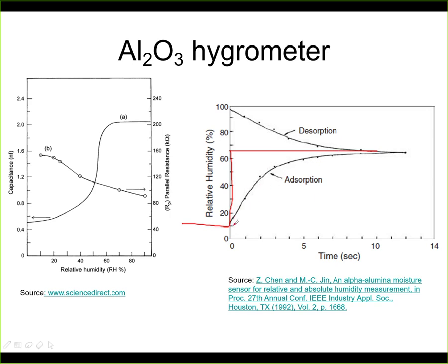You can see that this is a first order transient response, and we can simply measure the time constant. The time constant is done as a tangent here, so like this, and this will be my time constant of the sensor, so it will be somewhere around 3 seconds.